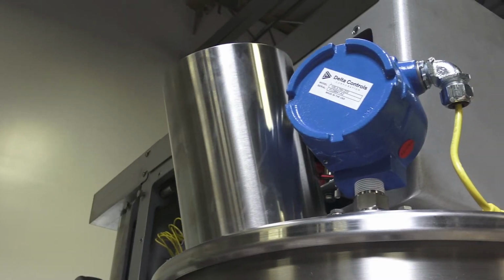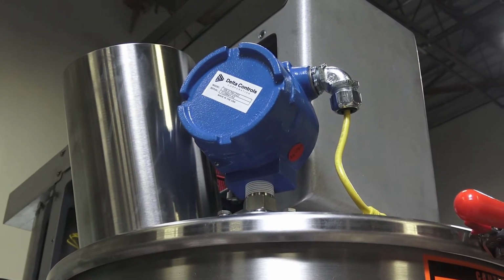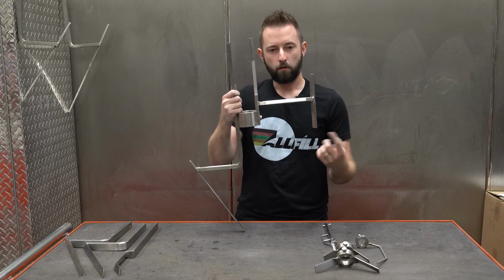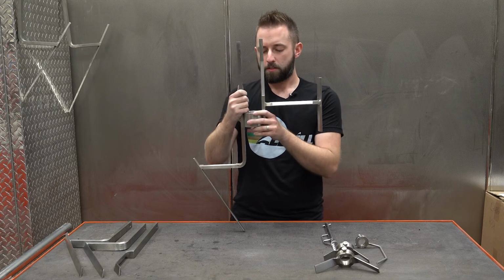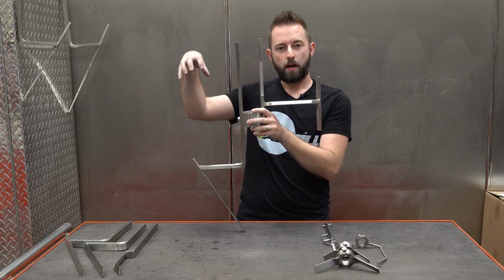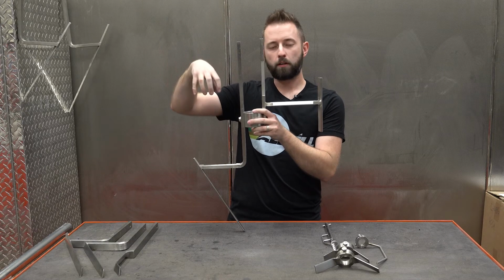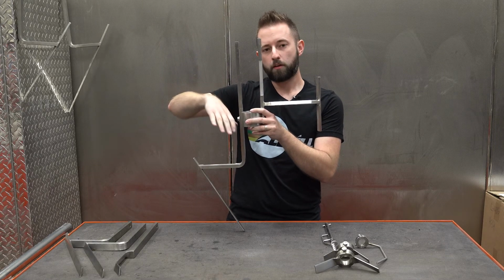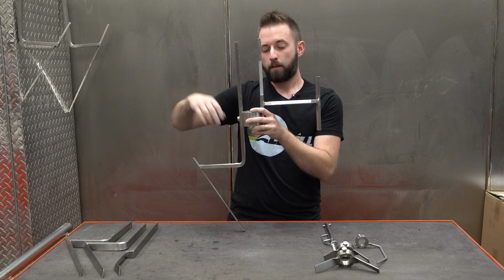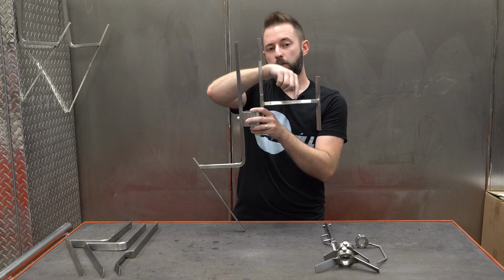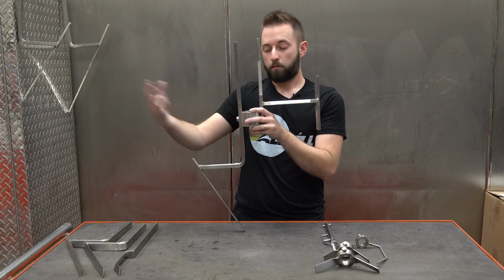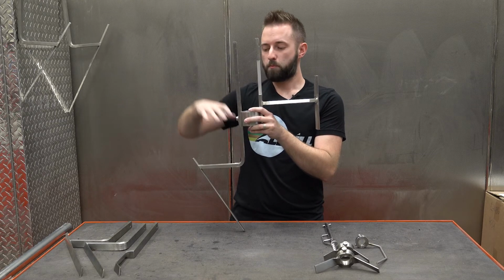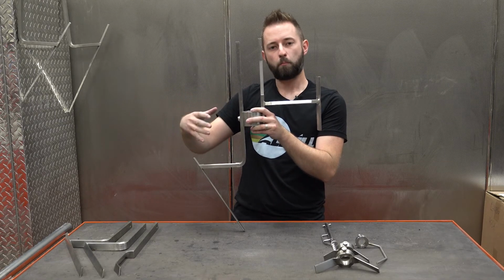We have level controls at the top of our hopper. Now these level controls, they rely on a consistent layer of product at the top of the hopper. So let's say you have an infeed system on one side. As that product's being loaded into the hopper, you're getting a mounding effect on this side of the hopper. The level controls over here, you can actually get a false reading from your level control saying that there's not enough product. Meanwhile, there's plenty of product that has been built up to one side of the hopper.